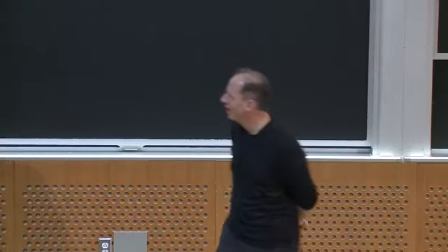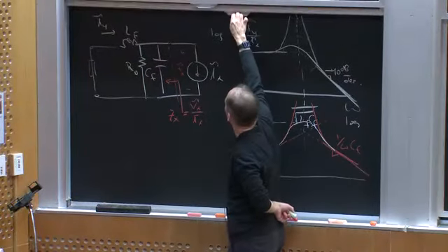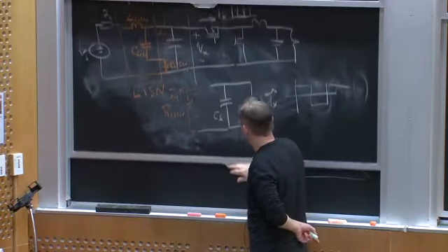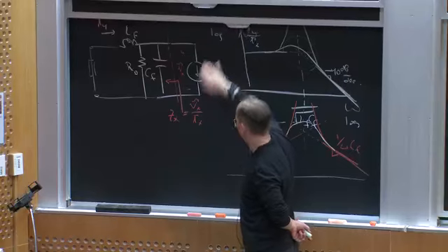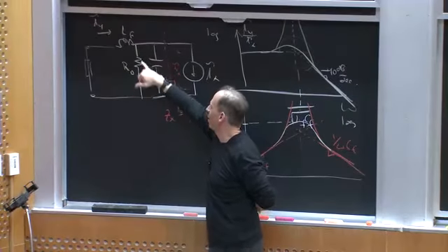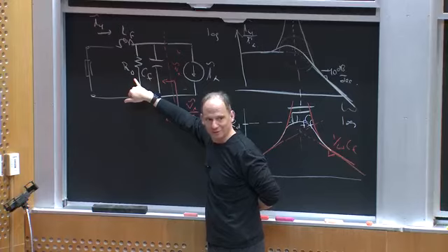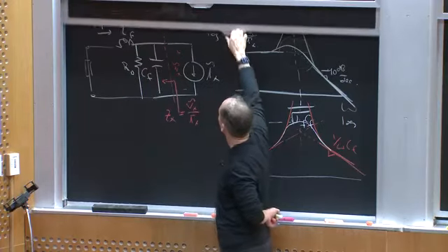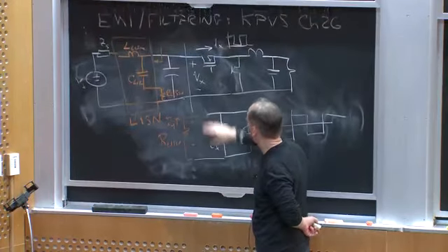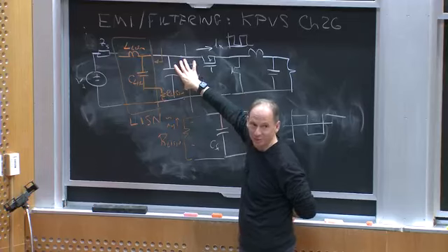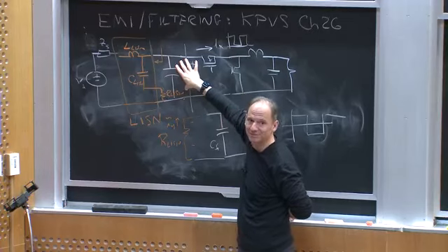Yeah, you're going to burn a lot of energy in this. If I come back to my original converter, I need to make RD, typically, if I want this to be nicely damped, on the order of square root of LF over CF or lower, for good damping. And I'm basically putting a resistor across the input of my converter. That's not very happy, okay?